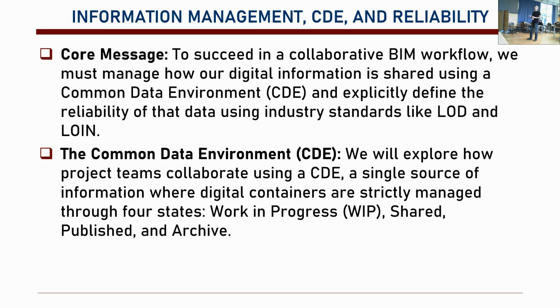The common data environment: we will explore how the teams collaborate using the common data environment, which is the single source of information in the project. There are digital containers, and it is strictly managed through stages: work in progress, shared, published, and archived.